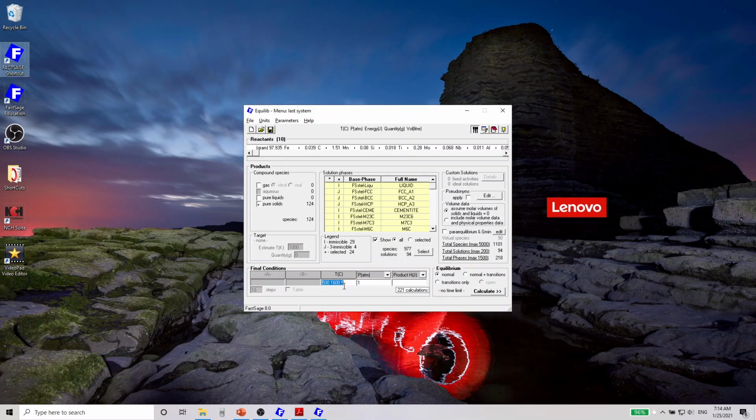the temperature range, which is starting from 500 degrees centigrade to 1600 degrees centigrade as final temperature, and with 5 degree centigrade as interval. We are selecting from 500 to 1600 degrees centigrade to cover the whole temperature range encompassing the austenite phase.